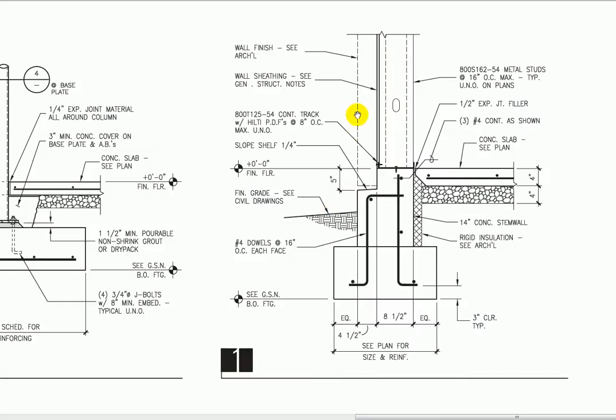Okay, like I said, when we were looking down, this was the outside line and these were the 2 top lines. So when we were looking down, we were cutting through the wall, and we were seeing this little bit of a ledge. The dashed line here indicates that it's the architectural exterior wall, and then here's the indication of the metal studs.